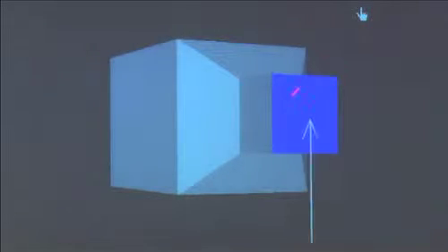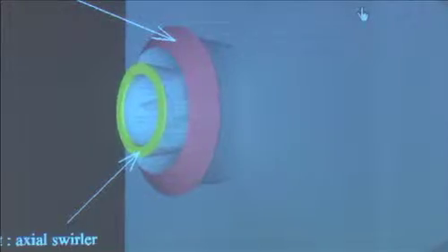You take the burner coming from a real engine, but you plug it onto a cubic combustion chamber so that you can do optical measurements. The chamber is terminated by a nozzle, which is square too. You need to add a nozzle to close the recirculation zone in these systems. Otherwise, the recirculation zone could be big and even get out of the combustion chamber.